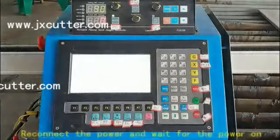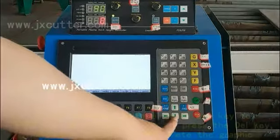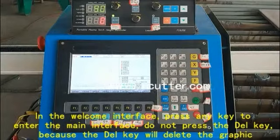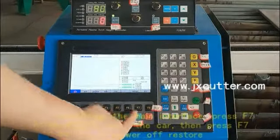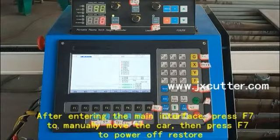Reconnect the power and wait for it to power on. In the welcome interface, press any key to enter the main interface. Do not press the delete key, because the delete key will delete the graphic. After entering the main interface, press F7 to manually move the car, then press F7 to restore after power off.